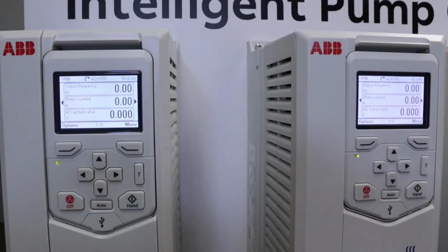At this time, we're going to look at setting up intelligent pump control. Each individual drive has been set up for its individual motors and motor parameters and any special parameters needed for the pump or fan that individual drive will be controlling. Now to set up intelligent pump control is easy, and we're going to use what we call the inverter-to-inverter link to move parameters around. But first we have to set up each individual drive.